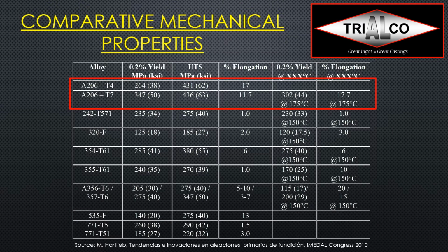If I want to have really high strength, well, then we said that before, the 200 series aluminum copper alloys are the right choice. In T4, they give us very good elongation at the same time, and if we want to maximize strength, we might want to give them a T7. T7, because that avoids stress corrosion cracking that we would get in a T6. We cannot do a T6 with these alloys, very important to notice. But here we're talking about yield strength of 50 KSI, tensile here is 63, and still above 10% elongation.